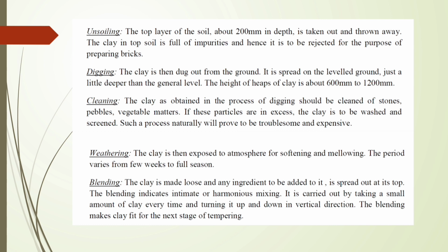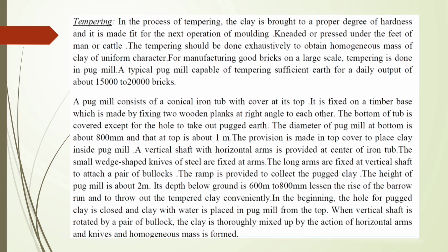Weathering. The clay is then exposed to the atmosphere for softening and mellowing. The period varies from a few weeks to a full season. Blending. The clay is made loose and any ingredient to be added to it is spread out at its top. The blending indicates intimate or harmonious mixing.